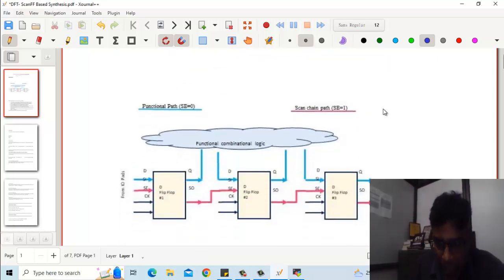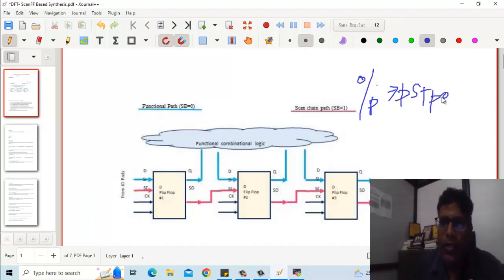In any sequential system design, what we understand earlier is that it's difficult to test any flip-flop. The reason is that it's a sequential circuit, so it retains the previous value. Unless I know the previous value, I may not be able to predict the next value, because the output is a function of the present state plus the previous output.